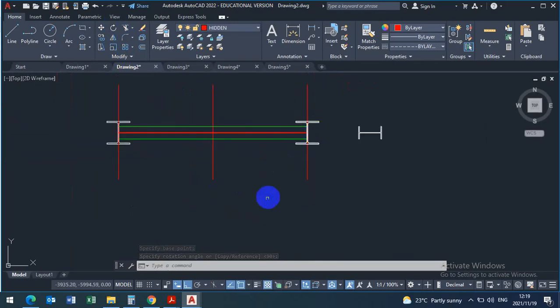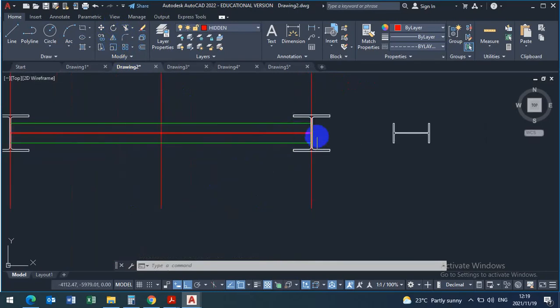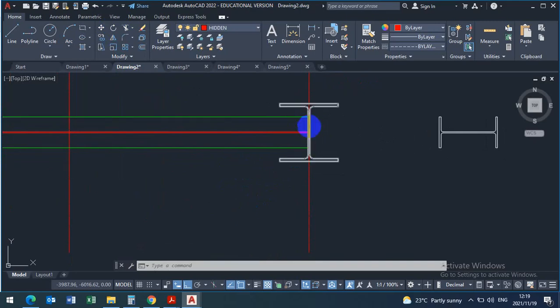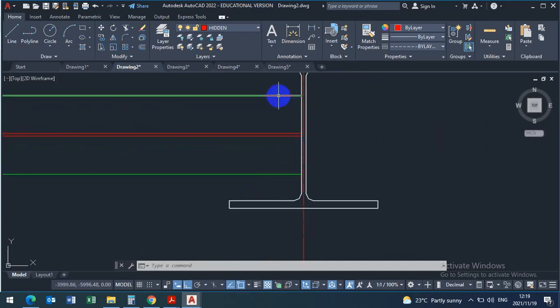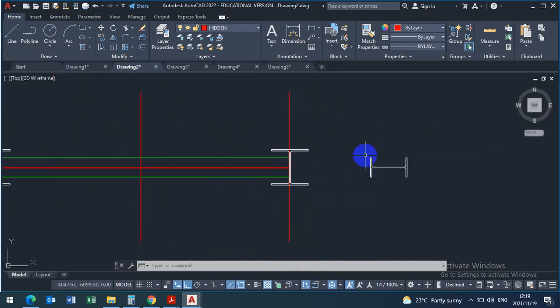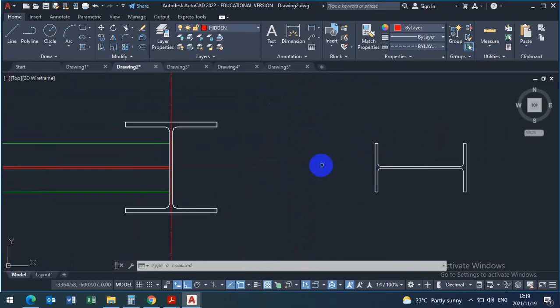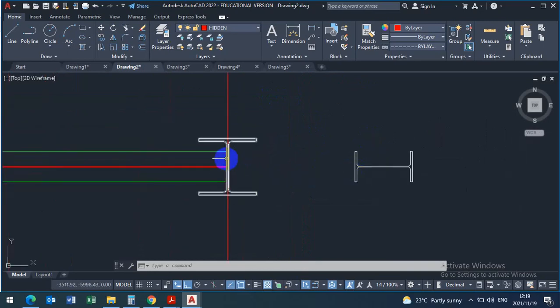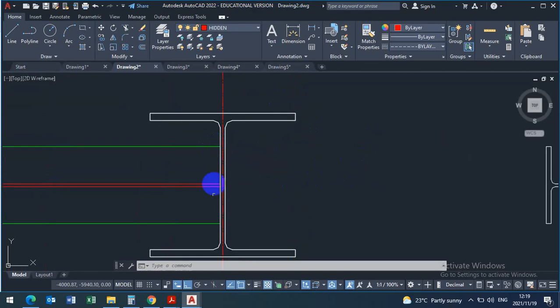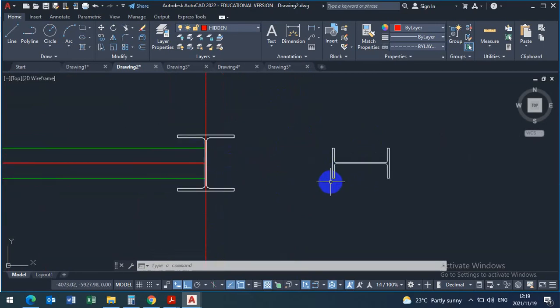Okay, so when we are looking from the top view, we are going to see how it comes in here, but the detailing won't be seen. Why? Because of this flange. From this green line to the green line is the surface of the flange, which is this flange here. That is the surface. So we need to know now at what position are we going to center the holes when we put the end plate. The end plate will come around this beam here. That's how you will see the end plate.